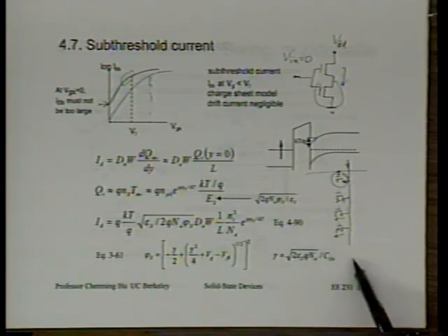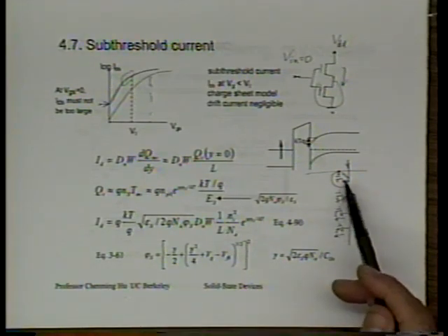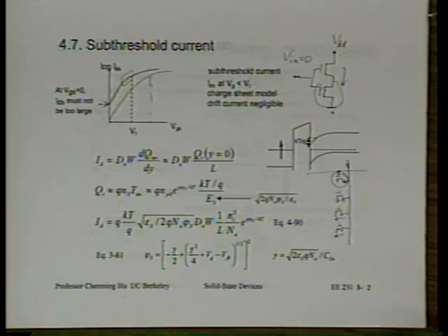And if we have thousands of these, they add up to the same amount of current that an on-state transistor will conduct, and you will just not be able to read it anymore. See that? So that's another example where we cannot tolerate large leakage current. All right. So there are several reasons we cannot tolerate large leakage current. In fact, I might as well point it out this time.